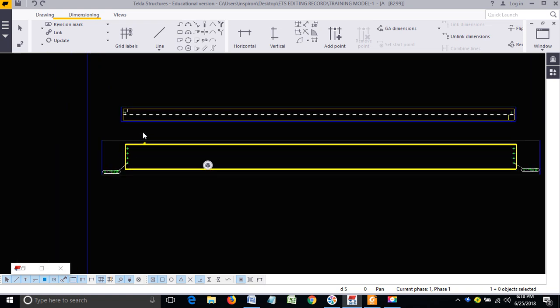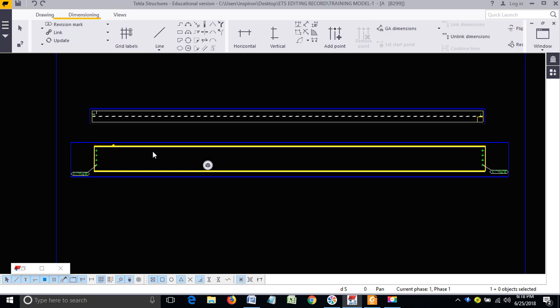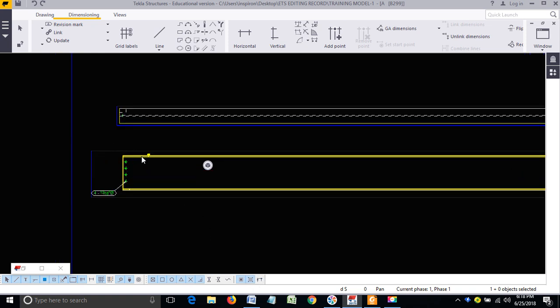If you finish the editing and later come to know that the orientation mark is wrong, then when you change the settings, it will look like a fresh drawing. Your editing and all your effort will be gone. So please make sure before editing the beam, the orientation mark should be on the left side of the beam at the top. Okay,